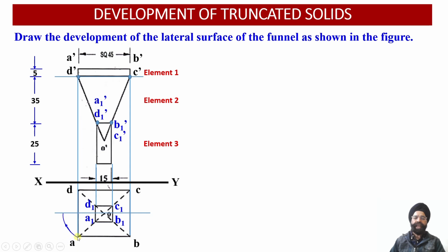Now we have to rotate this slant edge OA in the top view projection so as to make it parallel to the vertical plane. Once we rotate this apparent length projection OA and make it parallel with respect to the vertical plane, we obtain the point A2. So now the top view projection is available as OA2, and this edge is parallel to the vertical plane.